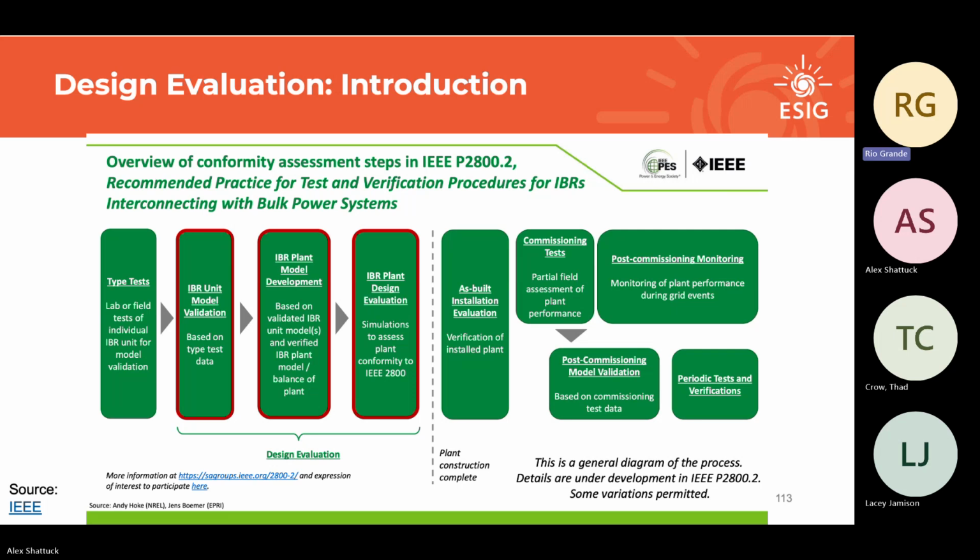I feel a lot of those calls where developers say, well, the utility put a transient overvoltage requirement just like the base standard in there. How do we test and determine that? Well, unfortunately, transient overvoltage is one of the two, in my opinion three maybe, major flaws of the base standard. We should never have had a transient overvoltage requirement in there because you can't test for it, really. You can't meaningfully test for it. The other two that get confusing are consecutive ride-throughs. And there was a mistake that I missed in the base standard for reactive power for type 4 wind.